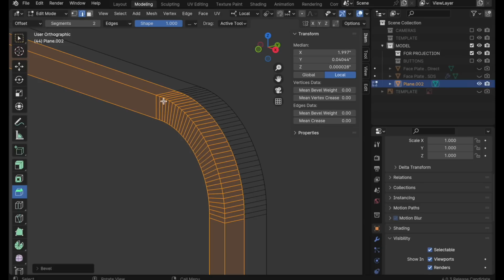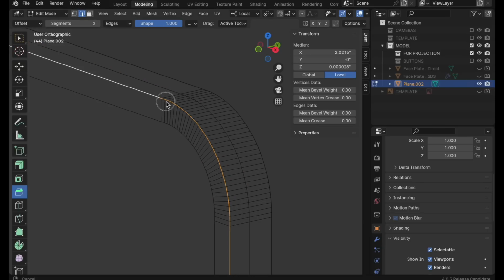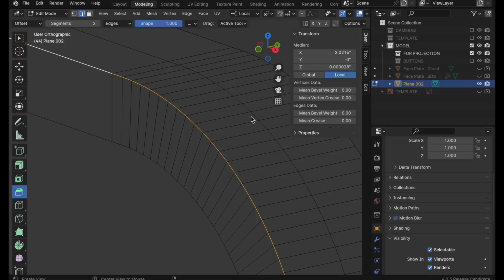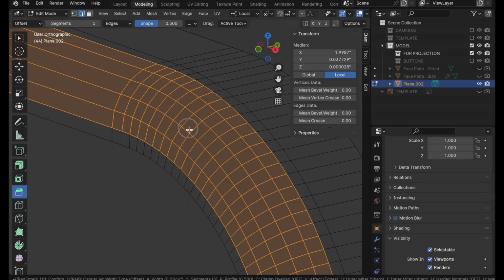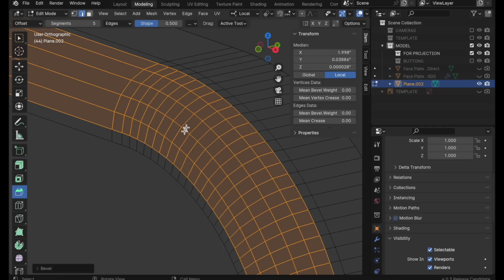So let's come in now. Let's turn off this template temporarily. Double click this edge, same loop that we were just operating on. Let's zoom down. We're still in the bevel tool. Let's switch over now. Let's do 5 segments with the default round shape of 0.5. Click, hold, and drag, and we'll pull this up. And go to about right there. Now this is important because the remnants of the segments 2 shape 1 inset are these boundaries here and here, which are planar to the large ngon and planar to this area over here. Those are very critical for controlling the shading on this.